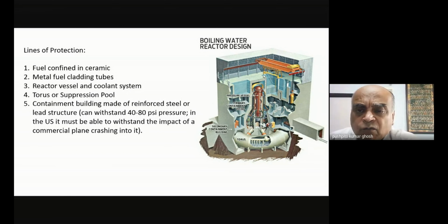So what one does is that this is then housed in a very special concrete casing, and it's massive. That concrete housing has to be able to withstand a pressure of something like maybe 8 bar. So you can imagine that it has to be designed very, very well.